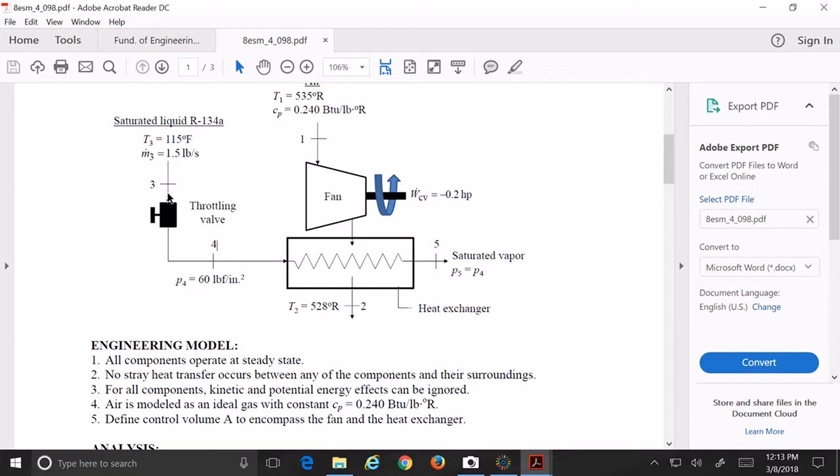Yes? So whenever you have a valve like that, you can assume it's a throttling device, in most cases. So generally the assumption is that it is isentropic, though we haven't covered that yet, so S3 will be equal to S4. Basically, on the throttling device you are not gaining or losing energy, you're just transforming the energy to go faster, no? And the same thing will happen for a valve. So a valve or throttling device means the enthalpy is equal on both sides.